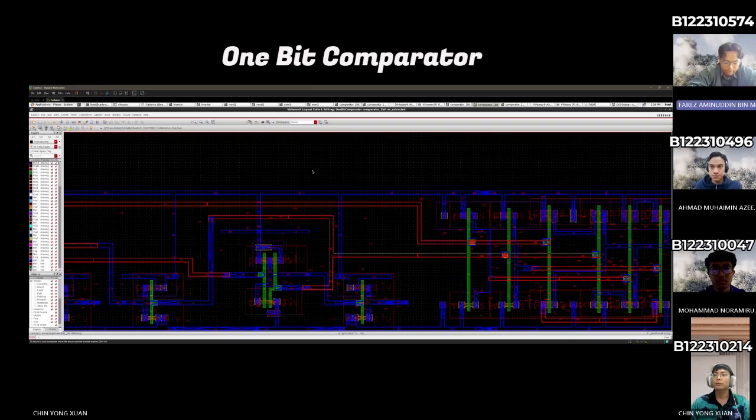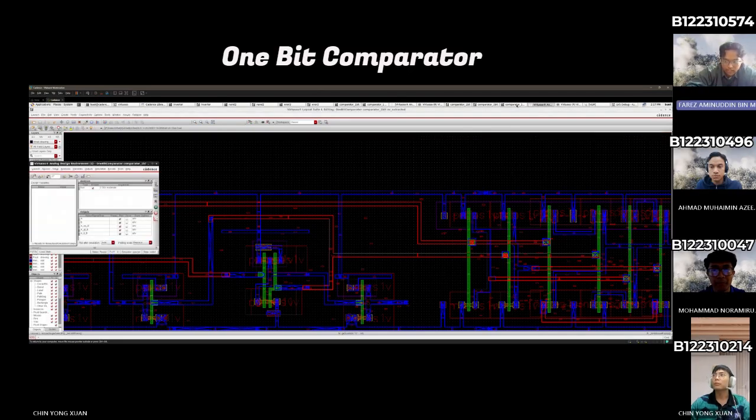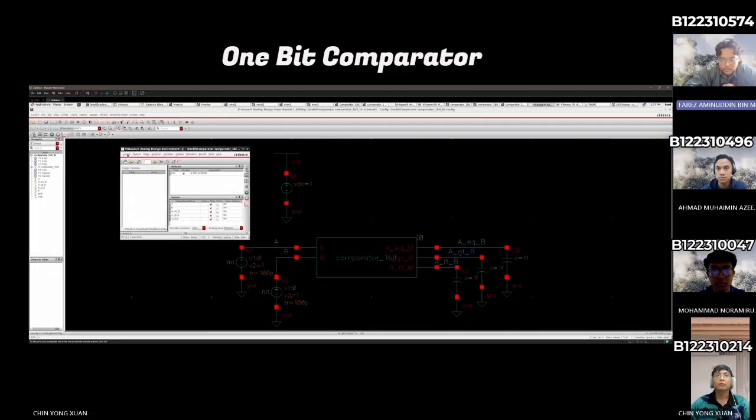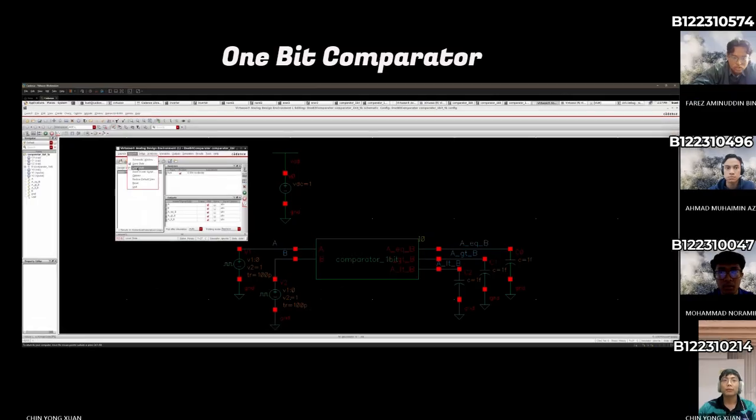By compiling these parasitic values into a highly detailed extracted view, parasitic extraction gave us the exact electrical model we needed for our final post-layout testing. Ultimately, clearing design rule check, matching layout versus schematic, and extracting our parasitics gave us the absolute green light that our design was ready for realistic simulation.